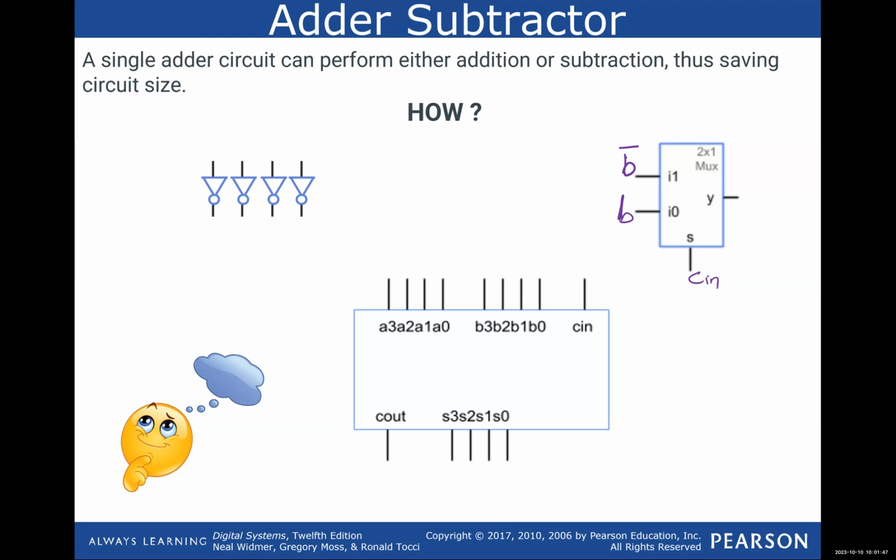Now, you need to explain what you've done. So, because this is the A's, they don't have anything to happen to them. This is going to be the deciding factor of plus or minus. Excellent. So the carry input is your decision. Do I want to do addition or subtraction? Okay, good. Up here, this is going to be the B3 original inputs.